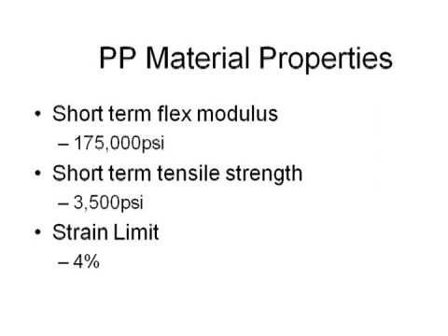While we do consider characteristics such as melt flow rate, Izod impact, density, OIT, and crystallization rate, for the purposes of this discussion, the properties that are most of interest to this group are likely the structural characteristics of polypropylene. These values include flexural modulus, tensile strength, and strain limit. Since polypropylene is a viscoelastic material, both short-term and long-term material characteristics need to be considered.